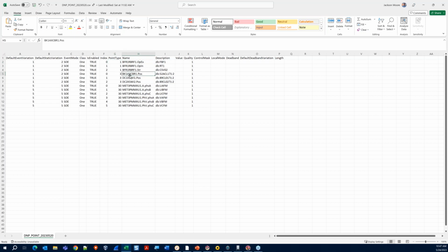Whereas this position value for my XCBR position in 61850 is a double bit indicating 4 possible states: open, closed, intermediate, and unknown. And that corresponds to a double bit in DNP3, which we define with point type 3 in the standard. And then finally down here at the bottom, we have some analog values, our 3-phase voltages and currents. And those are going to correspond to analog inputs, which are defined by the number 30 in DNP3.